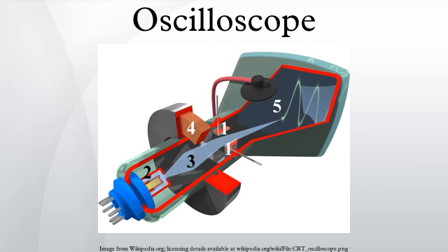Types of trigger include: external trigger, a pulse from an external source connected to a dedicated input on the scope. Edge trigger, an edge detector that generates a pulse when the input signal crosses a specified threshold voltage in a specified direction. These are the most common types of triggers. The level control sets the threshold voltage, and the slope control selects the direction.